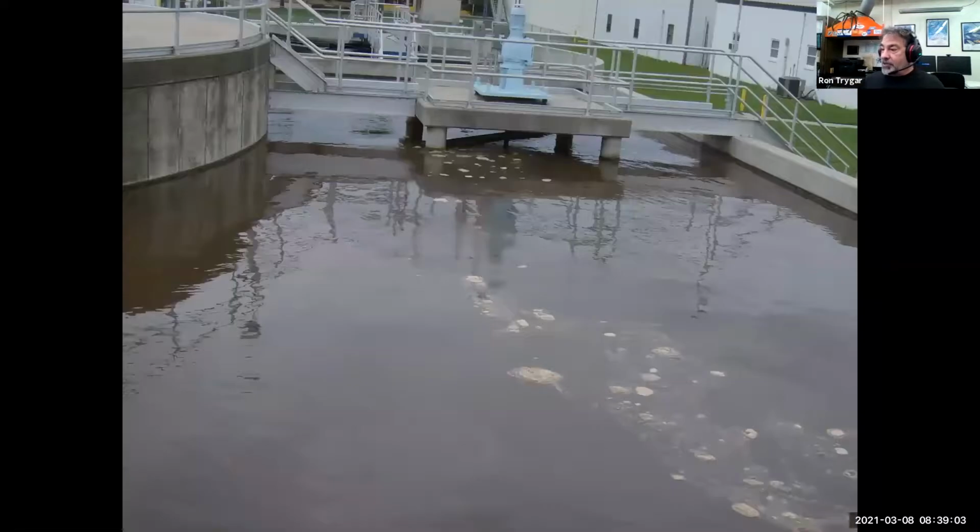All right. So here's another example of a pre-denitrification tank. There's a lot of these processes around the United States and around Europe known as the carousel process. It uses an oxidation ditch type setup where we have a pre-denitrification basin ahead of the carousel, or we'll call it the oxidation ditch process. The oxidation ditch is kind of on the other side of this wall here, and this is where the big mechanical aerator is putting oxygen into the tank.